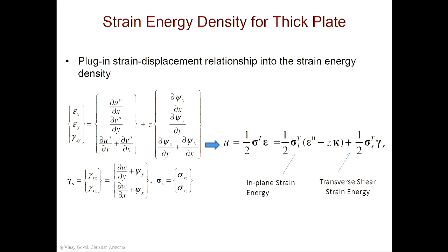That's my strain energy. And so I will realize here very quickly that I have the in-plane stresses, call those in-plane stresses sigma x, sigma y, and sigma xy. So that's a column of stresses there, okay? That column of stresses times this here. I'll call this epsilon bold naught plus z times this kappa bold. That's what I have there. So I'm just looking at the in-plane stresses separately. It's convenient to do it that way. You guys follow this? At least up to here?